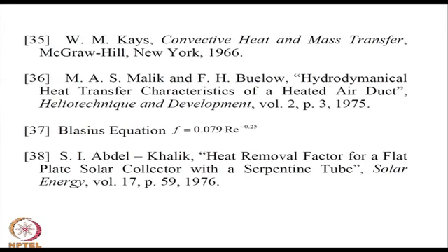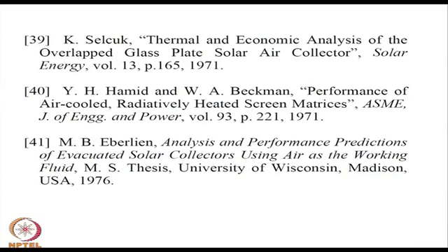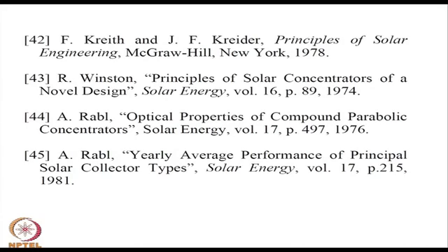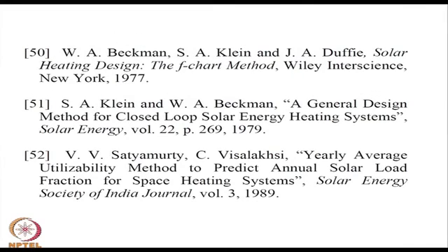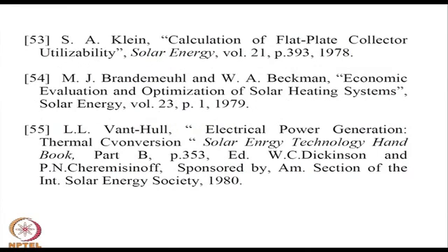So this is just the Blasius equation that gives you the frictional pressure drop, and these are all the additional solar collector geometries. Again, there is TRNSYS, another simulation program, and a computer program for the design of solar energy systems by Klein, Mitchell, Duffie and Beckman, and sets of data showing how to reduce and use a simpler data set rather than a voluminous one. Those advantages also have been found out, or how you can do that.